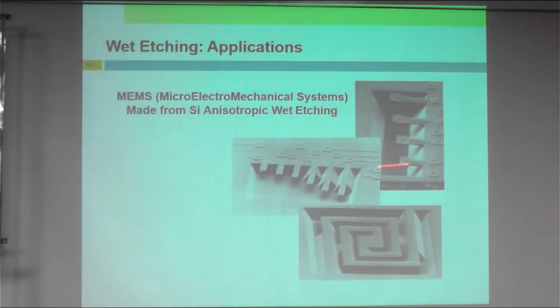And wet etching application. You can see that these are examples of microstructures that can be formed using etching, which is removal of materials from the surface. So everything using etching, maybe wet etching or dry etching, and overhanging structure. But of course, the process might be complicated, and it's not just a one-pass process but a few steps to form this kind of structure, what we call a cantilever beam, etc.